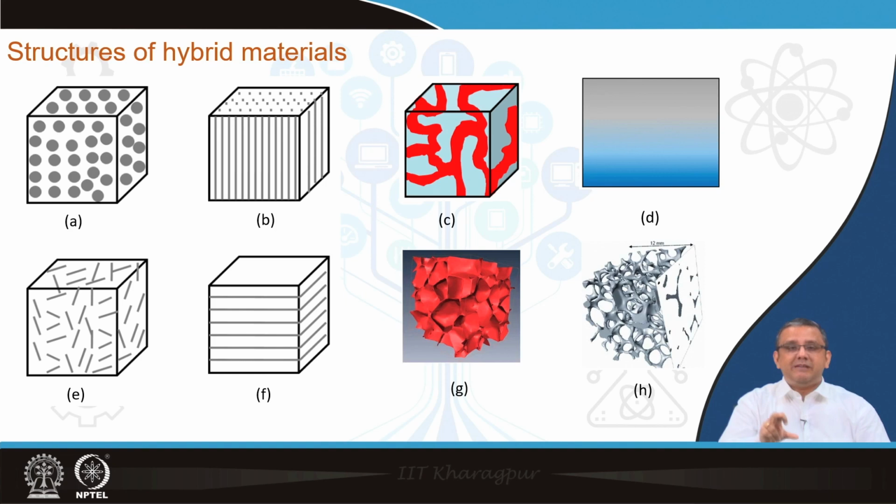Whereas, for continuous fiber reinforced composites, the fibers are all along one direction, the vertical direction, and that will provide the material with extremely high anisotropy. That means the properties along the fiber direction are good, and the properties along the transverse directions, the two horizontal directions, can even be poorer than the matrix.